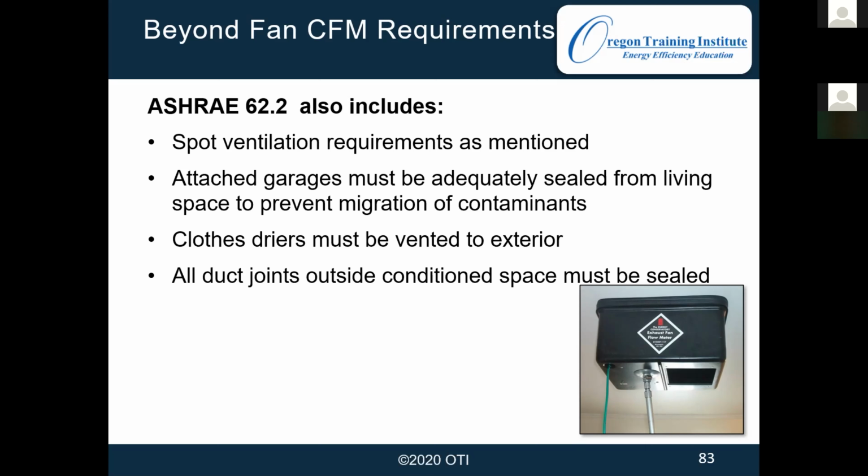They do have a standard on how tight they want the ducts, but for exam purposes, we'll just stick to the BPI requirement, which is 10% of the furnace airflow, not the square footage. It has nothing to do with that. It's the furnace airflow, which means now we need to know how much air is going through the furnace. We can measure it in a lot of the same ways we do exhaust fans, like with a flow hood or a flow plate or a pitot tube. Or if nothing else, we can check what the rated flow is at least.